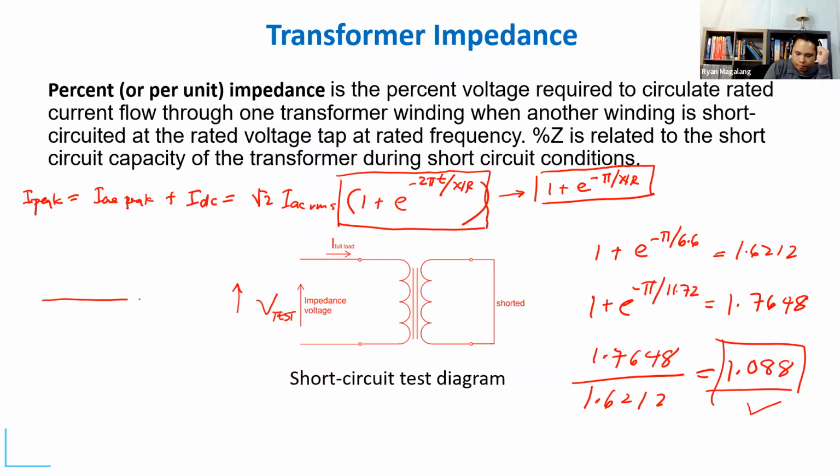Let's say you have a breaker here that is not passing the rating. Let's say this is a 14 kA breaker, and this bus has a 40 kA fault level.